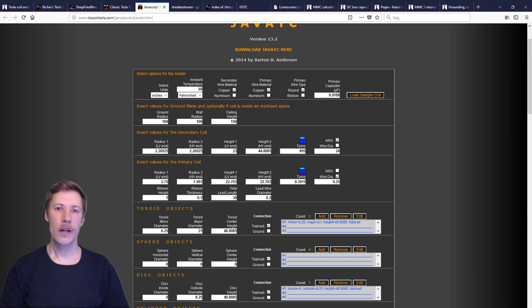But if your unloaded resonance is around 10% higher, then I would go for it, because when you detune your primary around 10%, you are around 5 to 10%. You are around the maximum output power detuning. So that is a pretty good rule of thumb to go for. But again, tuning is a very fine picking art, as this all changes with how the weather is that day and what is near the coil and so on. There's so many factors that really affects the resonance of the secondary coil.